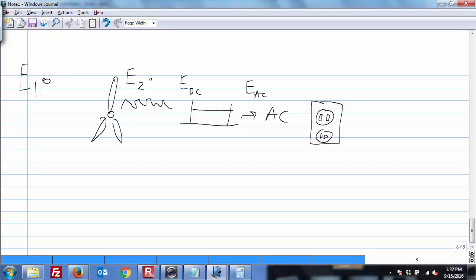Each one of these is going to have some efficiency. In general, if your lines are short, you might lose 1 to 2% through this. Every inverter, go stick your hand out an inverter, it's hot. So it's radiating, like that's its loss. Even the little electronics in the back of the room here, they get hot. They're radiating and losing electricity. So a good one's 93%. Yeah, 93% is a pretty good estimate, because there's no such thing as a perfect conductor, at least in these type of technologies.